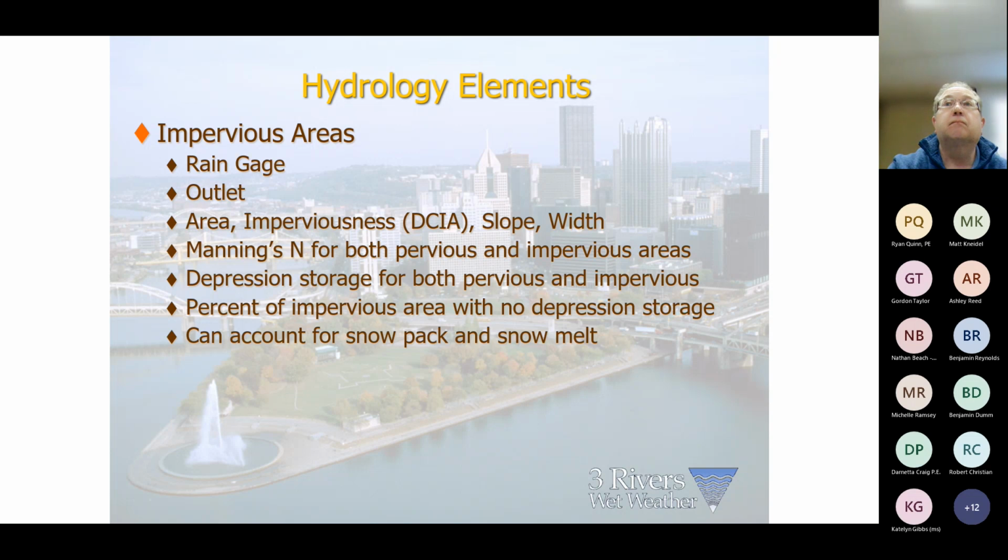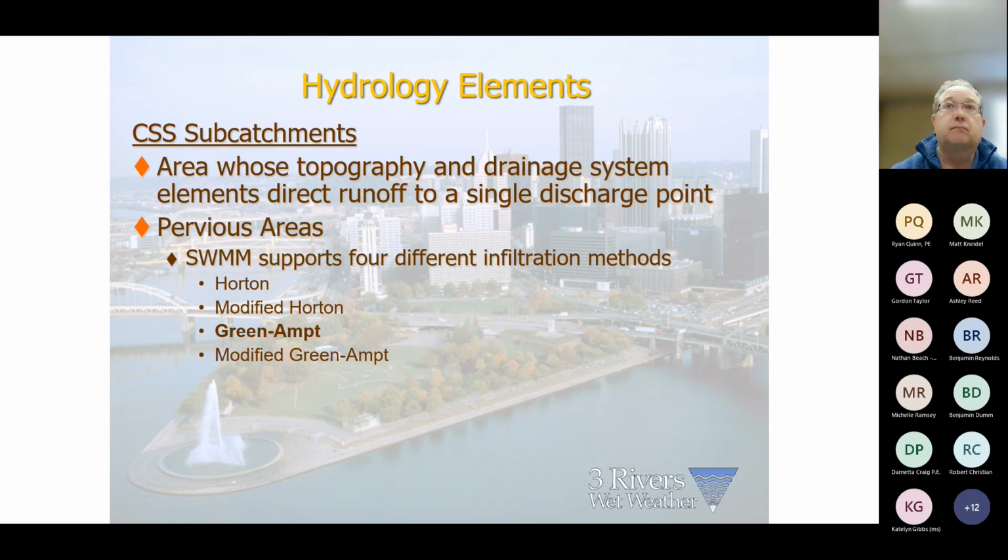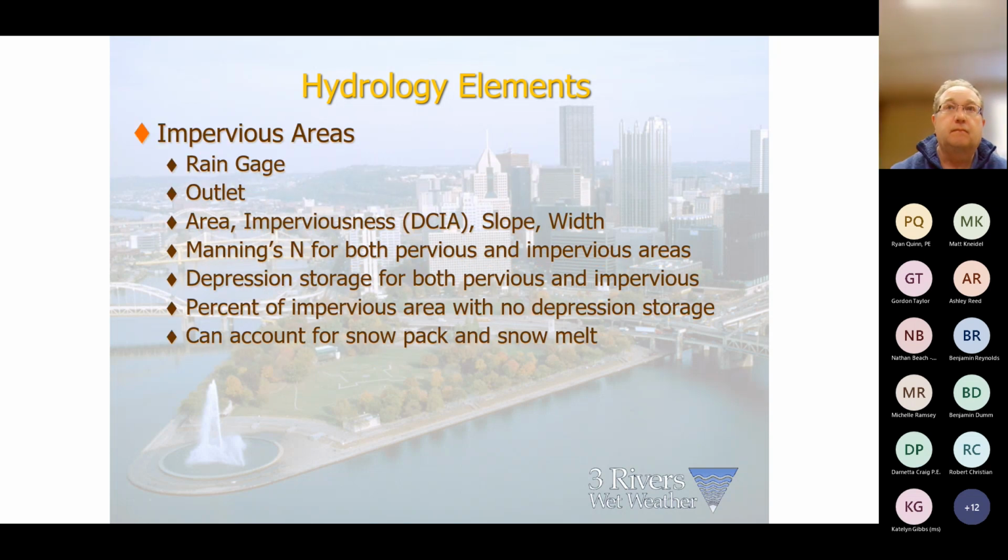And there are some other subcatchment parameters which are much easier to measure on maps. So as Brad was saying, if you have new flow monitoring data and it does not agree with the model predictions, and if you have the knowledge about your area that it has changed, usually there'll be more development in some subcatchments, especially bigger developments like a new mall.